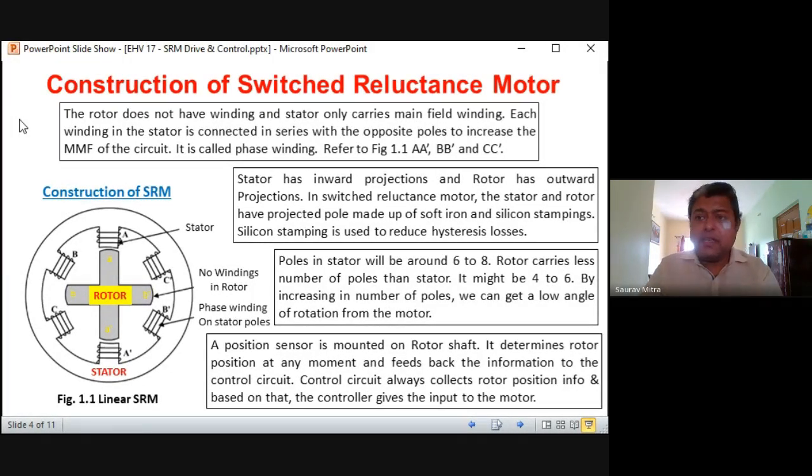Okay, depending on that, in BLDC also we are doing the same thing. We are always trying to rotate the rotor by one step. And in the next step again the control is changing. So we are keeping a carrot in front of the rotor. If now you are under the N pole, as soon as stator N and rotor N align, an S is generated in the next position.